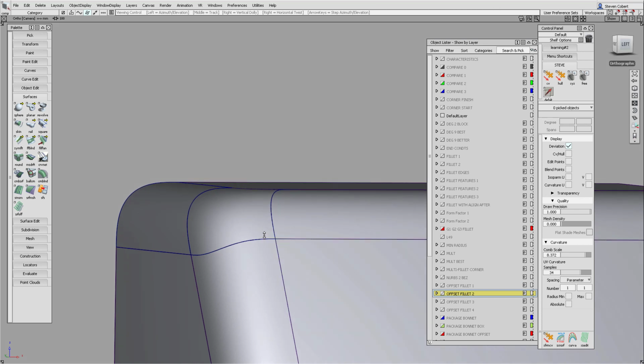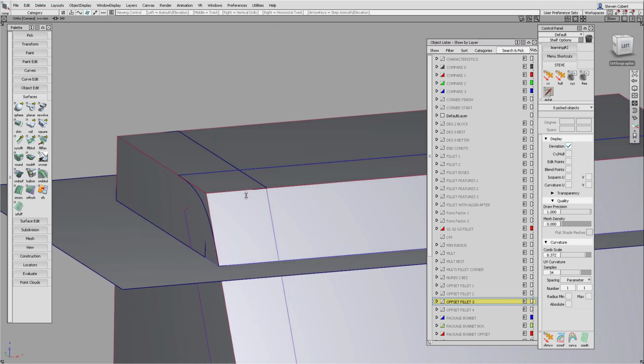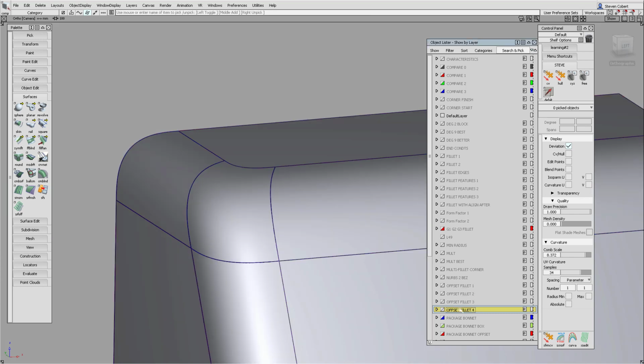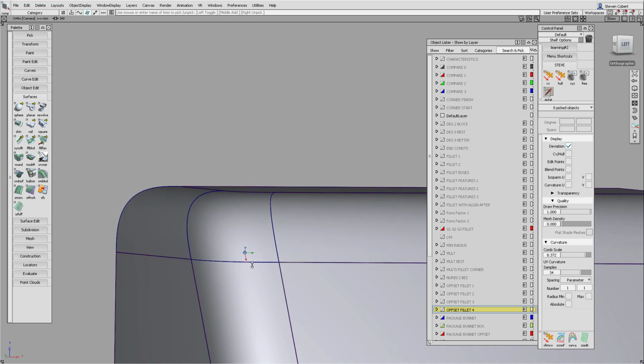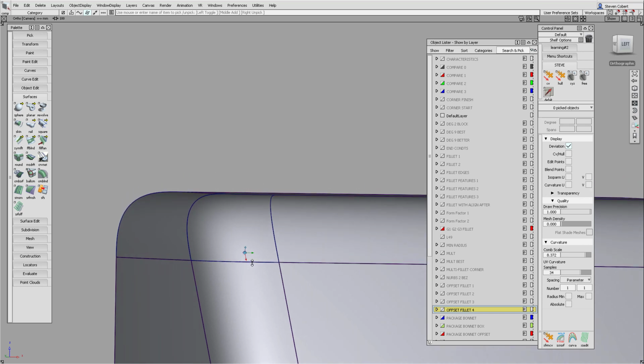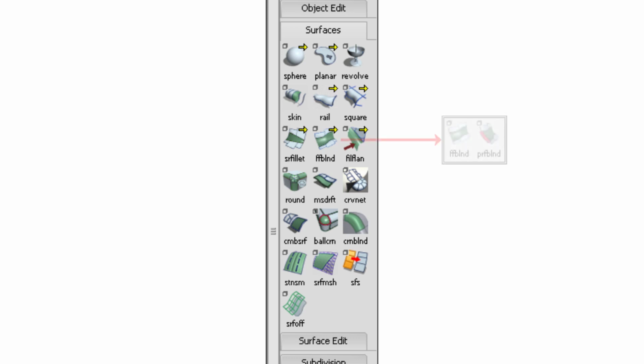In other words, we offset the top surface to create curves on surface for the fillet edges and the corner fillet. Then we would use symmetric fillet to give a totally consistent set of fillets. The corner surface is then very neat. This may not be appropriate in all these types of situations because it does result in varying radii on the top fillets.